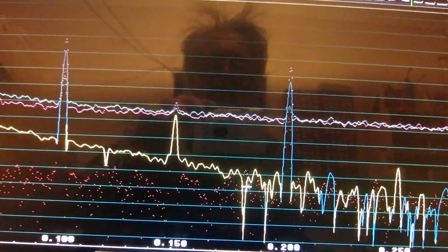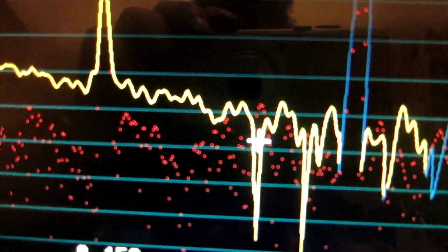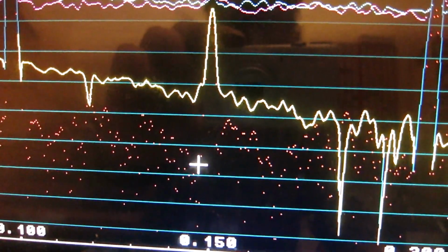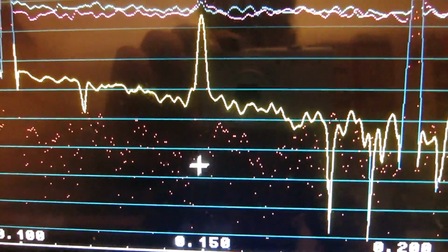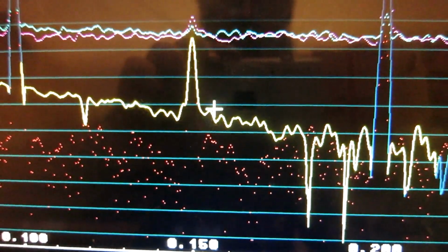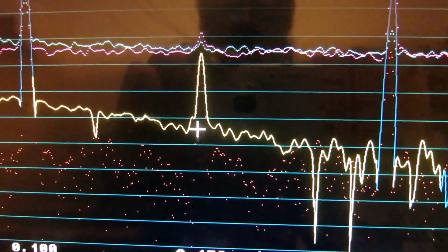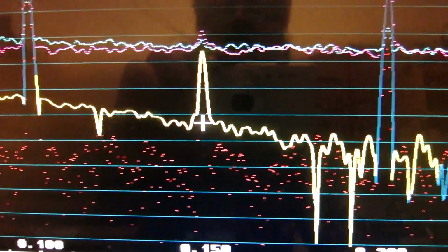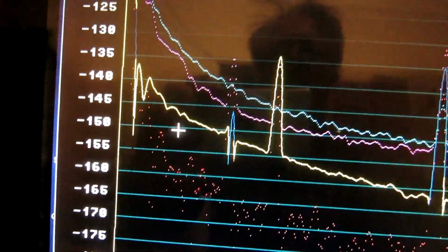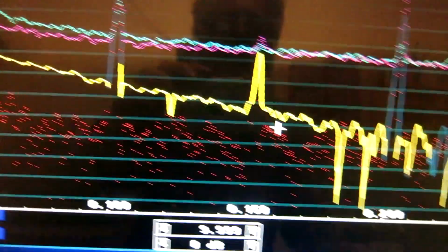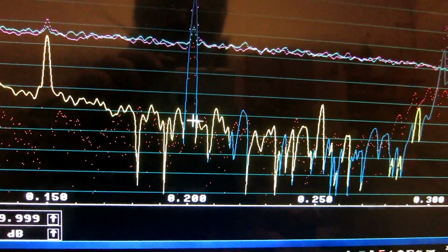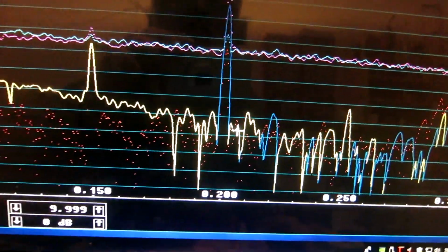I'm following with the mouse cursor, well, you can see on the video where the imaginary part is. And from about 150 Hertz I can read the noise sideband, the level of the phase noise, and down to about 20 Hertz here. But at 200 Hertz I cannot trust what value I might find here.